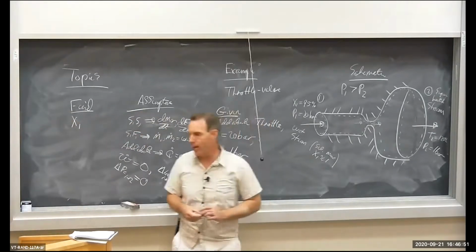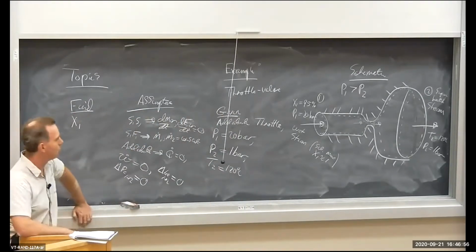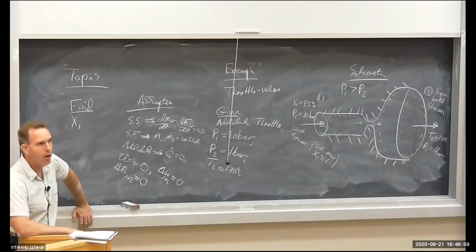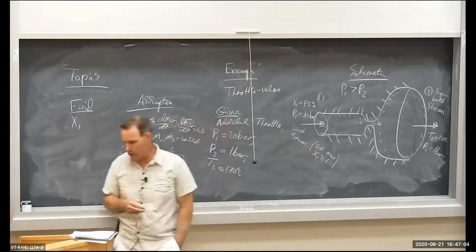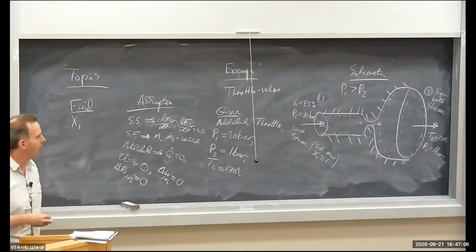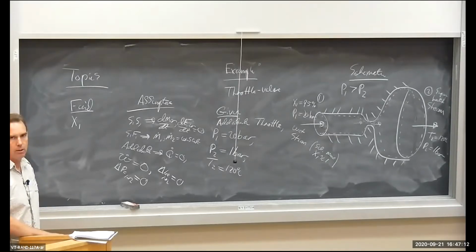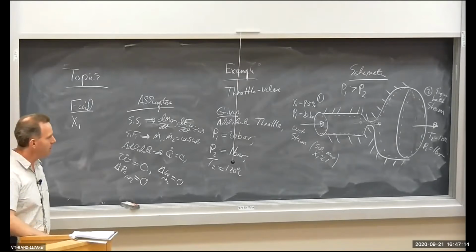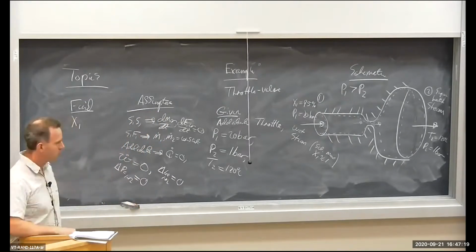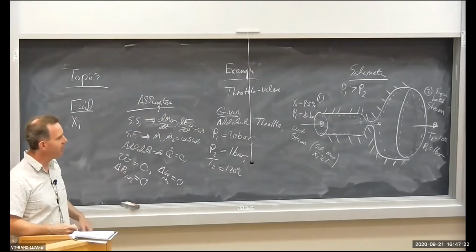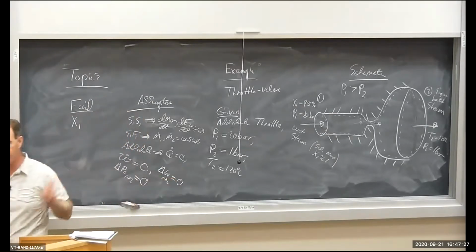And then we established that we started with a saturated mix, and we expanded to a superheated vapor. I wanted to spend a fair amount of time on your first example today of the energy balance for an open system. We'll move on next time to two more complicated examples involving work-producing or consuming devices, turbine, compressor, or nozzles and diffusers, devices which do something a little bit more than this throttling valve. The throttling valve is isenthalpic.